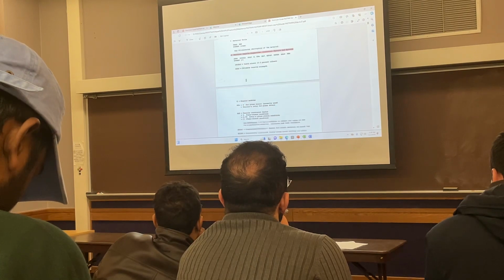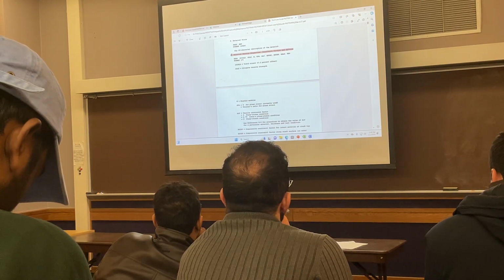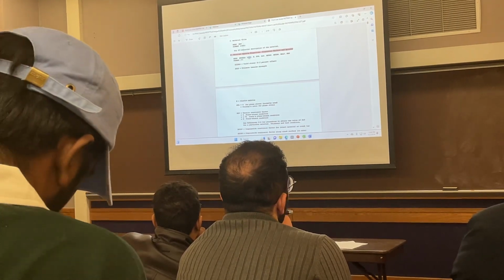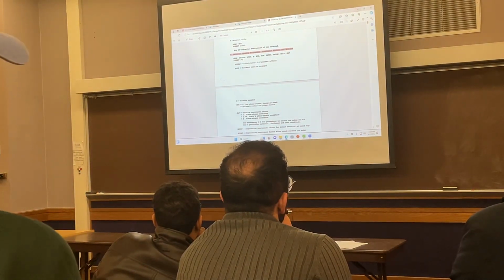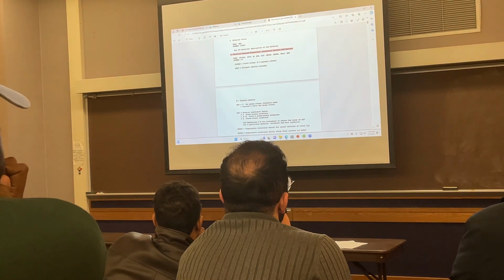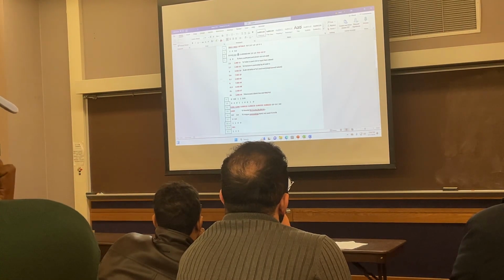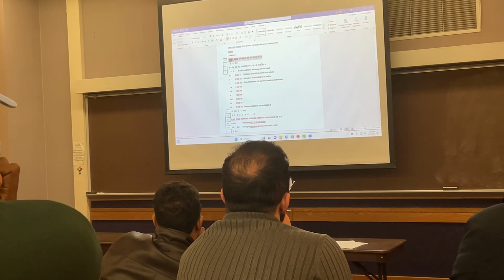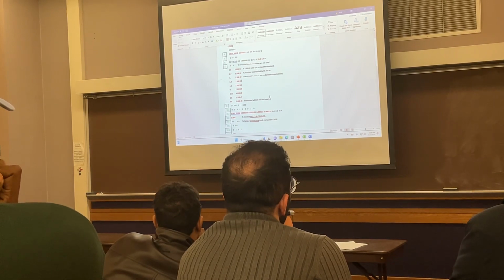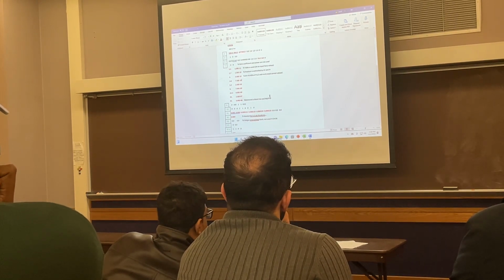For example, number 4 is material properties: yield stress, ultimate, Young's modulus. These are the information defined as section 4, which corresponds to this part of your input file. Those that I highlighted in red are the most essential ones that you need to change in your input file.